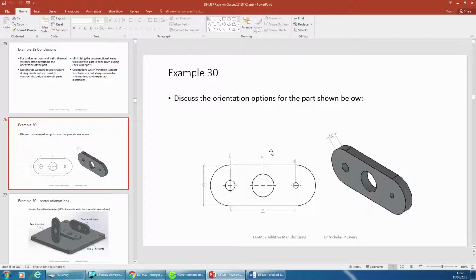In this one, it's not particularly complex, but what we need to consider more in this instance is that you've got potentially a relatively thick wall. You've got cavities. An accepted size of those holes for this to build accurately is that they be no bigger than 10 mil.